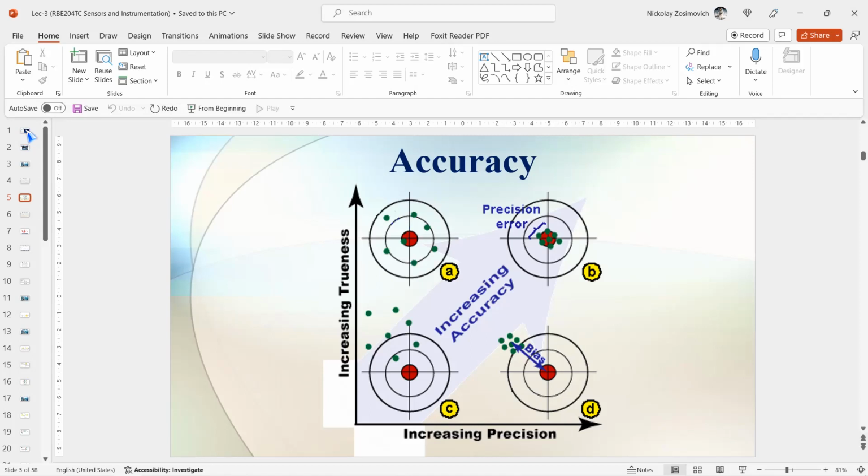Why? Because it may or may not include particular imperfections of our sensor, like nonlinearity, hysteresis, and drift, and may be only valid under strict conditions. So, precision is not the same as accuracy. Actually, the term precision should not be used in any case to avoid confusion.